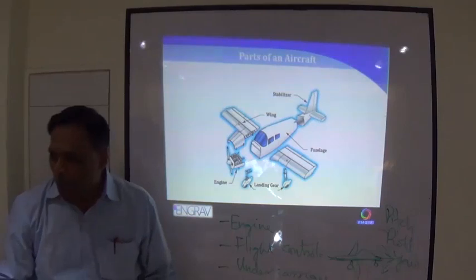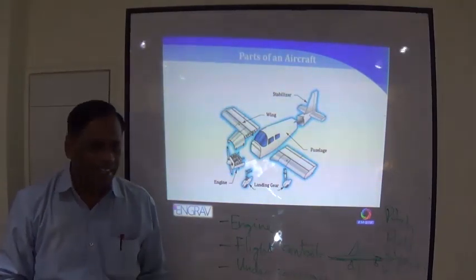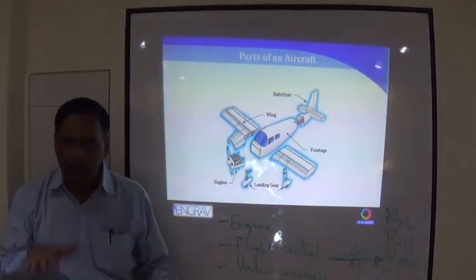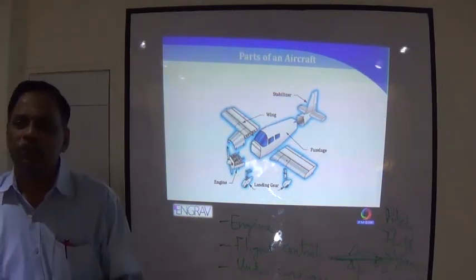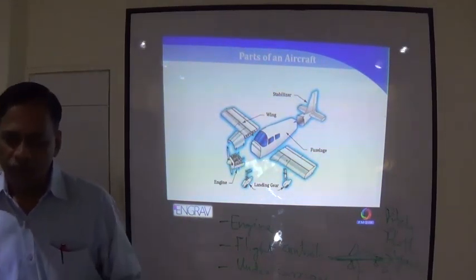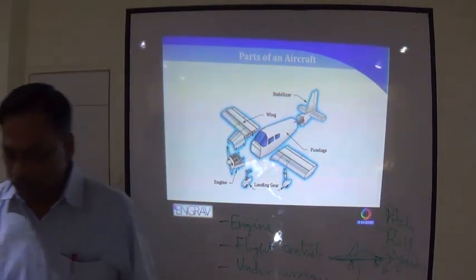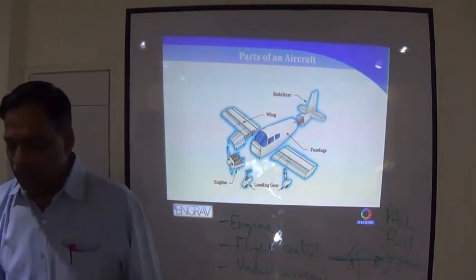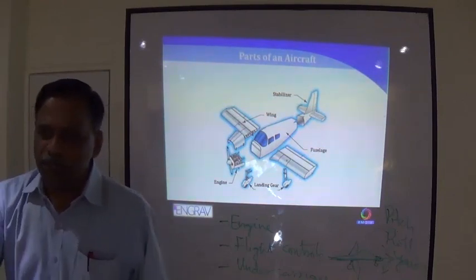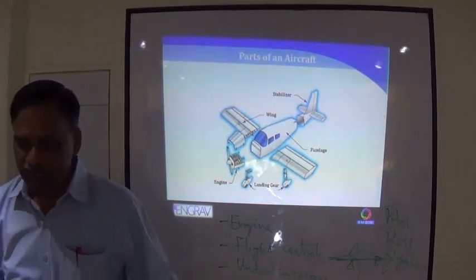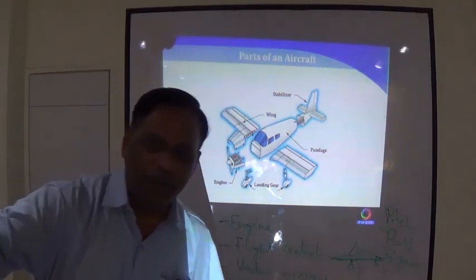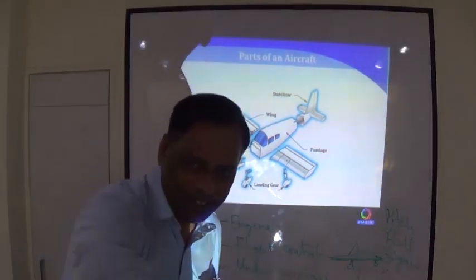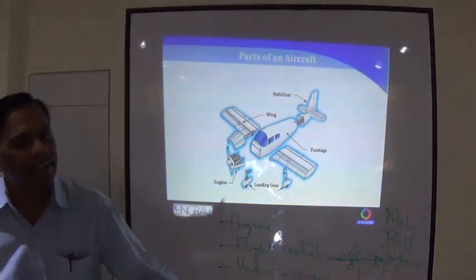In the aircraft, when you're flying, if you want to turn to the left or right, you don't do what you do in a car. If I'm flying like this and I want to turn left, I don't abruptly put my controls to the left. What I do is I do a roll first, and then put the control. So it's a coordinated left turn.